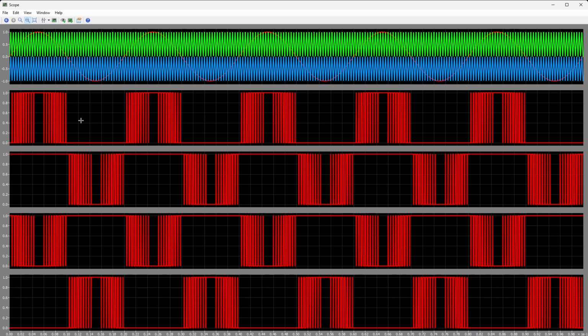You see, according to the pseudocode of the pulse width generation, once we have the sine wave in positive direction, S1 is now changing constantly and the state of S2 is then fixed, S3 is changing, S4 is fixed. So this logic is now implemented correctly.